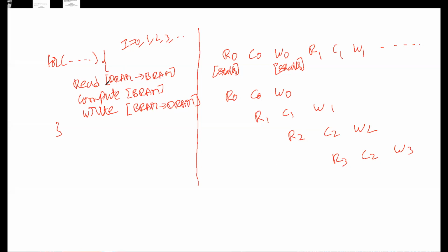If you see, there will be some kind of overlap. For example, if C1 and R2 are overlapping, so if C1 is doing computation and the input buffers are manipulated, then the data gets overwritten. In order to solve these kinds of problems, we use techniques called double buffering or ping pong buffers, etc. So these are the architectural approaches that you use to keep your CPU busy.